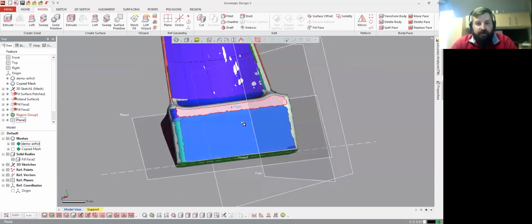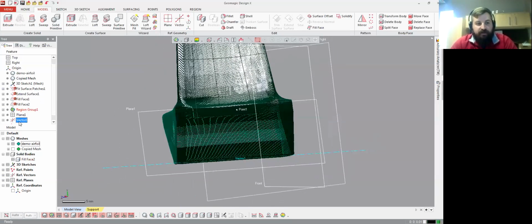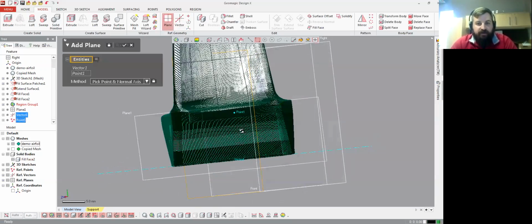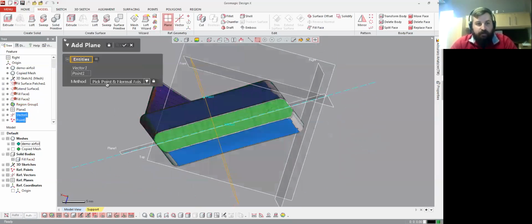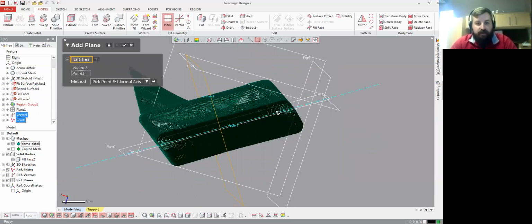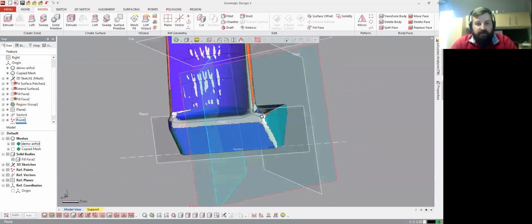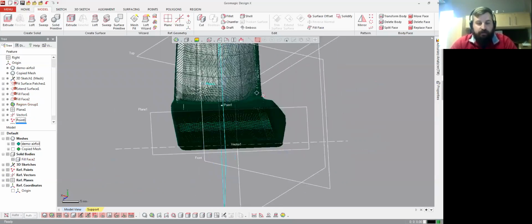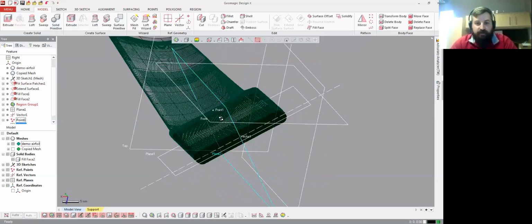So it just drops a point on that surface, and if I pre-select both my point and my vector out of my tree, and go into the plane function, again it tries to do the calculation and it creates a point and normal axis plane. So a real nice, easy way to get a reference that's kind of perpendicular to the sketch plane, to create a sketch plane in the proper direction using a bunch of reference features.